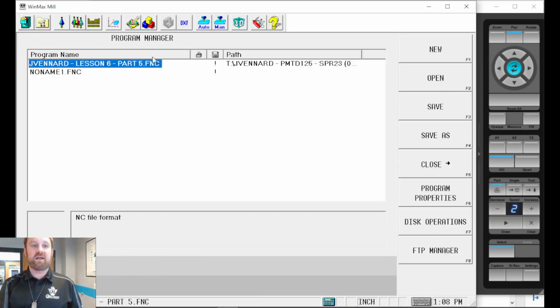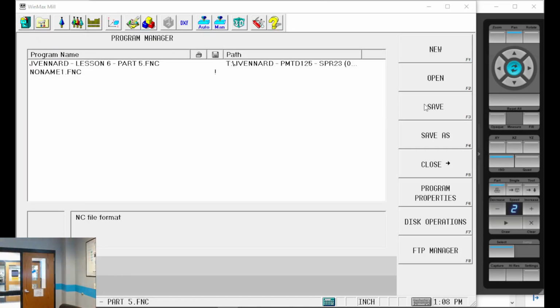If yours looks good, I'd go and hit save. That way it's out. Go back to it. Okay. So the same thing we had to have the other day. Go back to your program. Your G43 line. Well, you got your G1 right now. It's not. I know. Hit play over there.